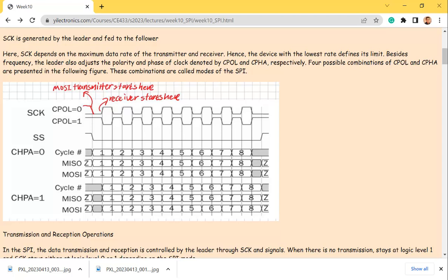Another reason I can tell it's not a 2-layer board is if you look at the pins for SDO, SCK, I couldn't even see the traces connected to SCK. Could you? Did you see a trace connect to SCK?